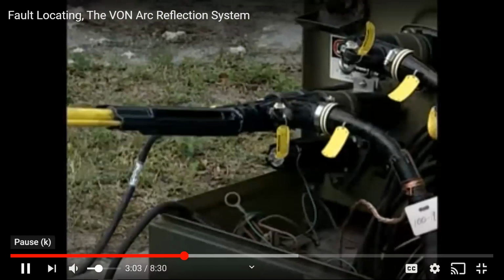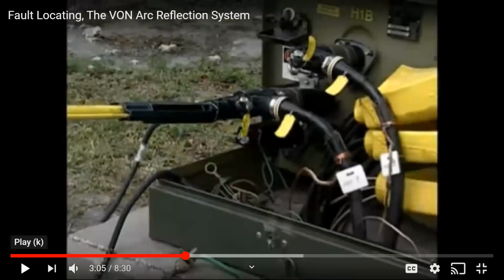Okay, so we're at the point right now. This is direct buried cable. In the previous video, the guy high-potted this span of conductor right here and found a fault on it. For safety reasons, he's going to re-ground it again. The next step is, now I need to locate the fault. This is the bad primary span. I know that. Now I've got to find out where it's bad.